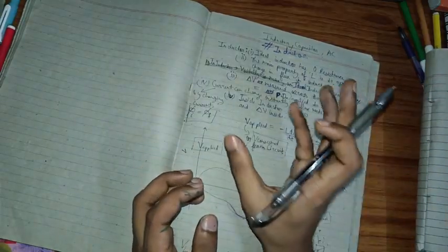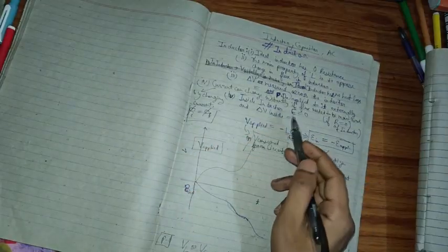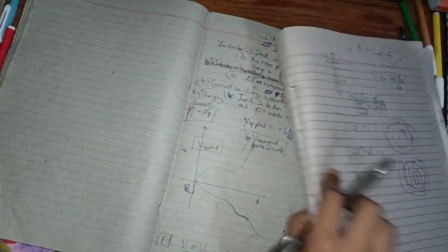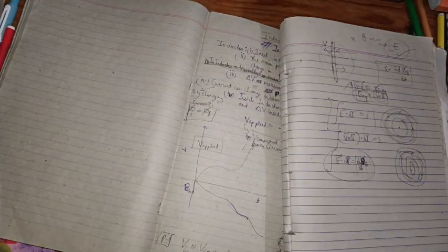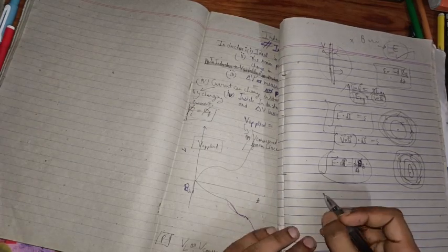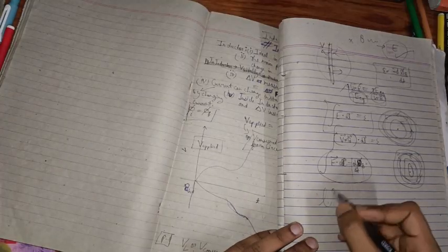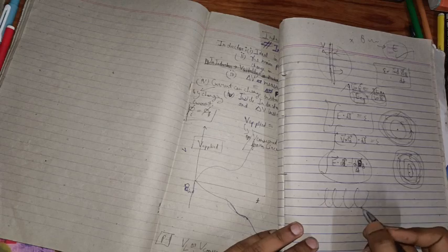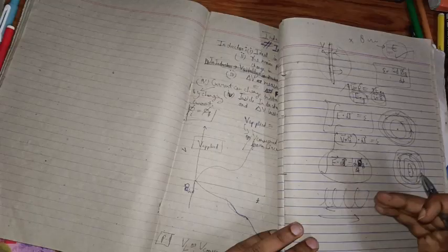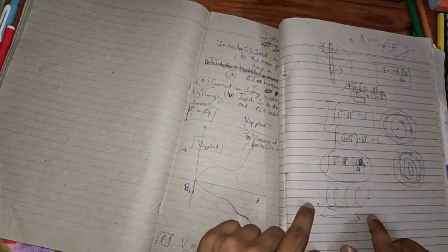And in actual, let's say there is an inductor here, and inside it there will be some EMF in the back side. When the applied voltage is in this direction, then the EMF induced will be in this direction. But it does not mean that the net potential difference measured across it would be zero. In actual, the potential difference measured is equal to the V applied. So V measured is equal to V applied, even though there is a back EMF, that is not what is measured here. But still there is electric field inside equal to zero. It is a complicated case, but just memorize this.